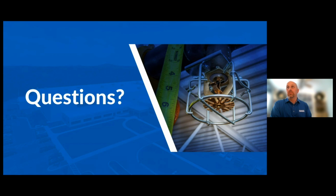And this is going to be an interesting one for you. I want to hear your answer. What is the difference between a lithium battery sidewall and a standard sidewall? That is a good question. First and foremost, I'd say K factor. It's an 11.2 K factor. We didn't hit on the amount of water that we're applying, but it is 60 gallons a minute. So that's something that we can deliver through that K factor with a reasonable pressure rating of approximately 28 to 30 PSI. And more importantly, how does it differ from a standard sidewall?